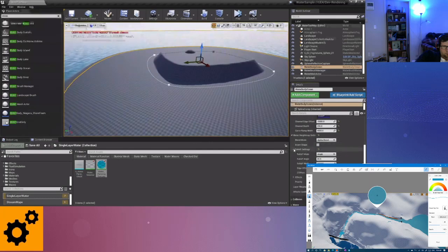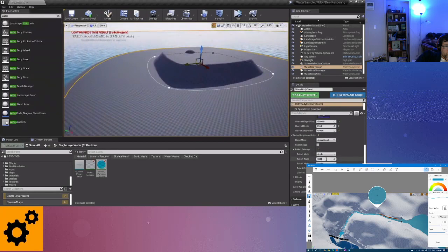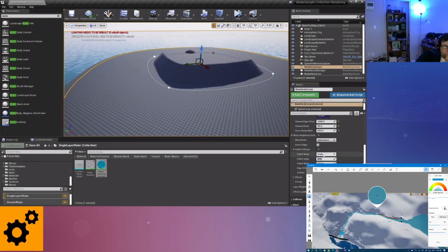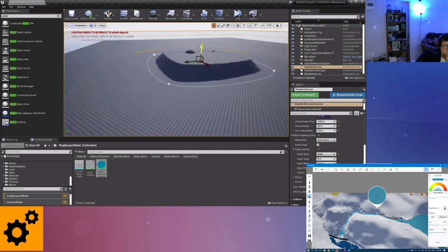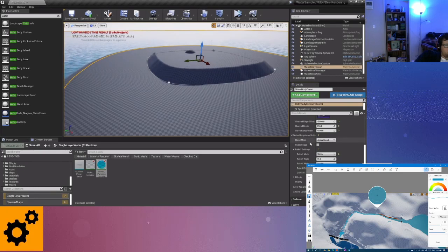We're going to go ahead and stick to the fall off settings for now. And you'll notice that right now this is in angle mode. So as I move this thing down, it's essentially going to cut the rest of the terrain at an angle. And you can change that angle to be shallow, steep, or keep it as it was. Or you can also set it to width mode, in which case it's not going to be an angle, it's just going to be a constant fall off. So you can kind of control exactly how that's going to apply. And the edge offset here is kind of separate from the curve offset. So you really have separate two-way control for your edge offsetting, which is pretty powerful.